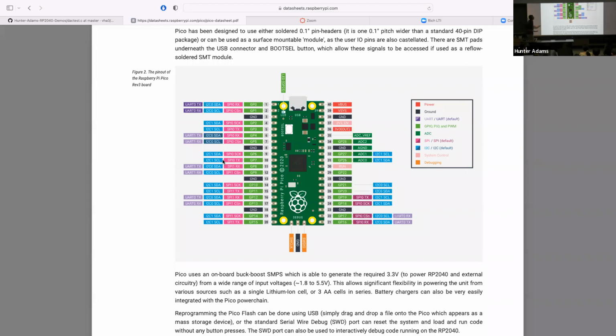If we wanted to interface with the DAC through, say, this set of pins as opposed to this set of pins, why? I don't know. Maybe we want to use some of the other functionality that's possible for these pins. Maybe we want to use this I2C channel, which means we can't use it for SPI communication. Then instead of using SPI channel 0, we would use SPI channel 1, because that's the SPI channel that maps to the pins that we want to use.